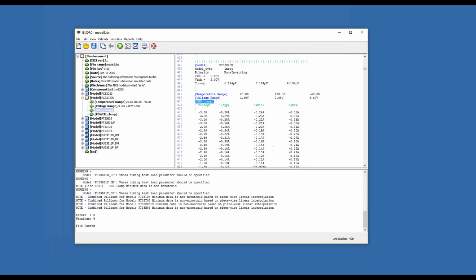And so this is a warning, okay? You'll see a warning in your simulation tool, and the question is whether this is going to cause you a problem in your simulation. It depends on the tool and on your simulation results. Again, this is one of the things where you really can't fix it yourself. Even if you did zero it out, you might change the characteristics of the clamping when it turns on and off. You have to go back to the IC vendor and say, you probably have an error with this, you should fix it. And if they can't fix it, then you're going to have to decide if it's a big enough issue that you don't want to use it for simulation.